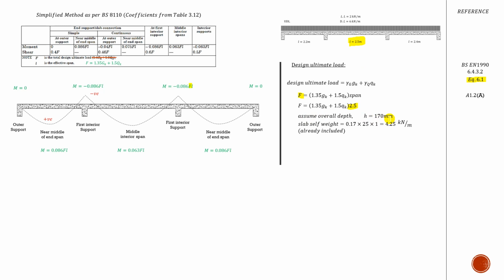There is another method, which is by referring to the table that gives the effective span over effective depth ratio, so that you satisfy the deflection requirements. You set your depth so that it satisfies the deflection requirements, and this is the first step that we might start with in order to give an overall depth of your structure member. Right, so what we have to do now,